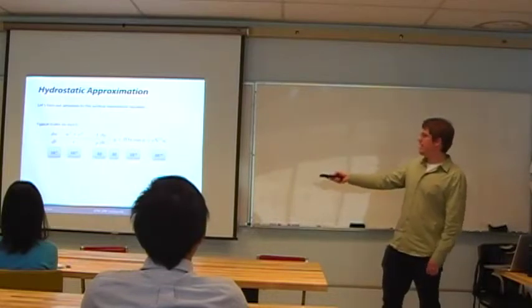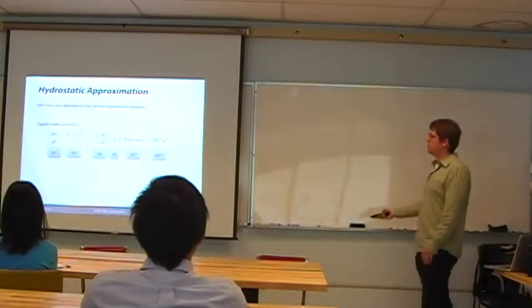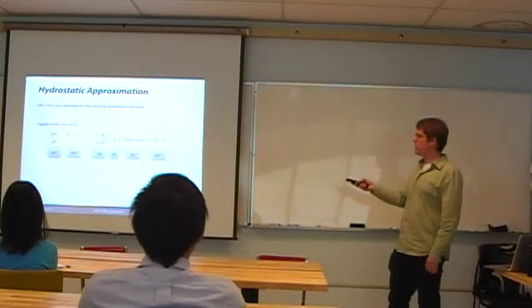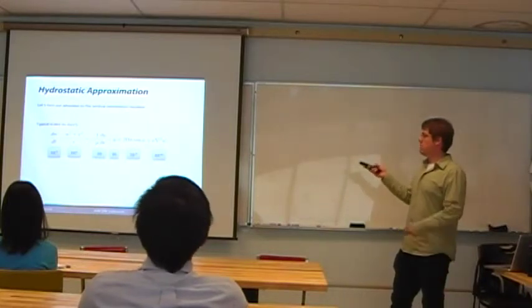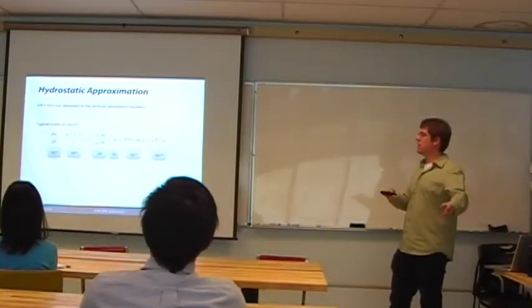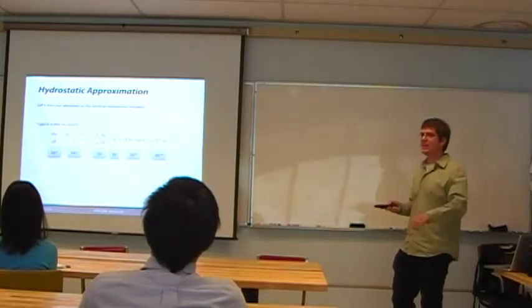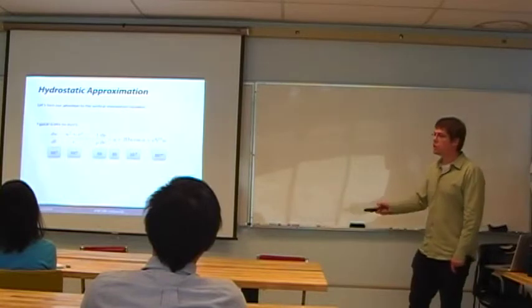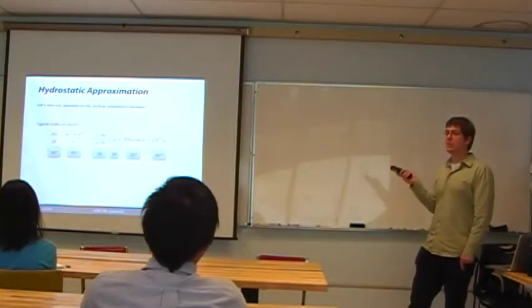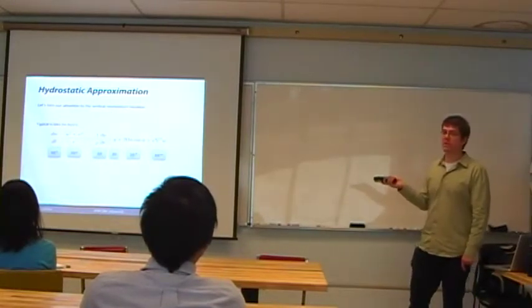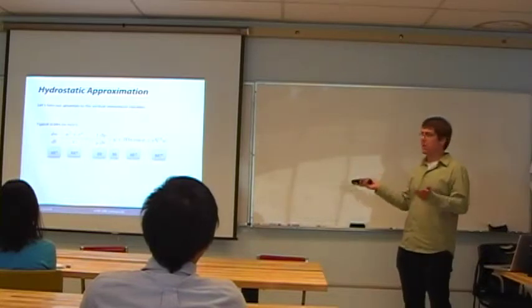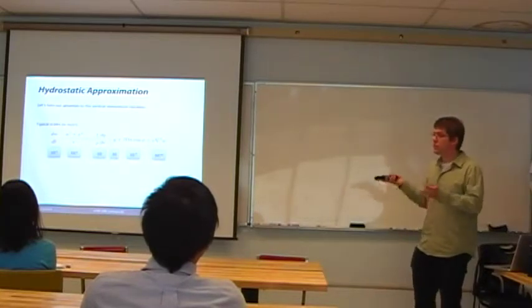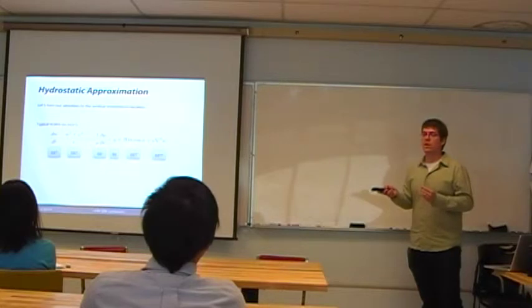This term is 9.8166, etc. So many decimal places. Calculate this very, very tiny difference, and then that finally gives you the vertical acceleration. Consequently, this equation turns out to be absolutely terrible for approximating vertical acceleration. So you can understand why. If you're ever taking the difference between two numbers which are very, very close to one another, there's a lot of room for error.